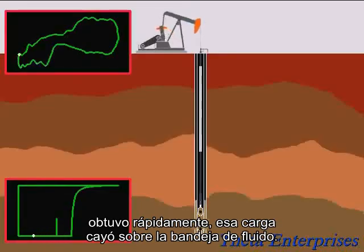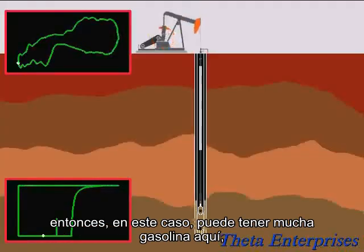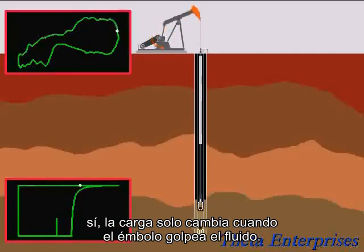See how fast that load fell on fluid pound? In this case, you can have a lot of gas there to help cushion the downstroke. Yeah. The load only changes when the plunger hits the fluid.